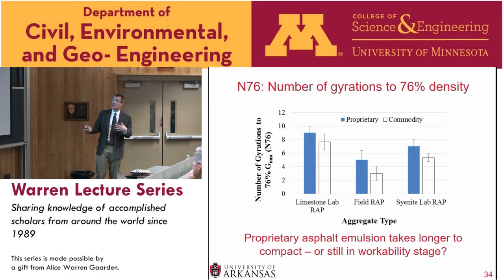and then we also switched the wrap to a syenite. So limestone and a syenite aggregates have very different properties. They have different charges, they have different chemical compositions, and when you think about asphalt emulsions, with those emulsifiers surrounding each droplet, the properties of that aggregate is very important and can change what type of asphalt emulsion you may use.